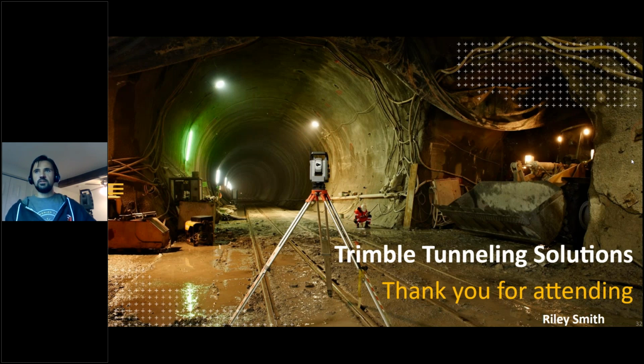Yeah, it's a complex question because for the control surveyor in a tunnel, how many targets and where you set them is probably one of the biggest challenges. The recommended type of traverse that's run through tunnels is typically a double braced traverse, where you're essentially zigzagging through the tunnel and having a redundant measurement in each setup.